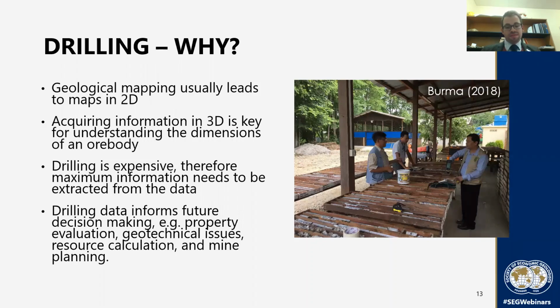Drilling is quite expensive depending on the techniques you choose. And therefore, it is very important that we geologists extract the maximum amount of information from the data that we obtain in drill holes. Drilling is very important because it delivers the information for future decision making, such as property evaluation, if you screen different properties for their mineral endowment, but also geotechnical issues, slope stability, and excavation factors, resource calculation, and mine planning.